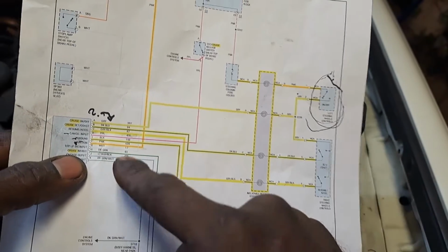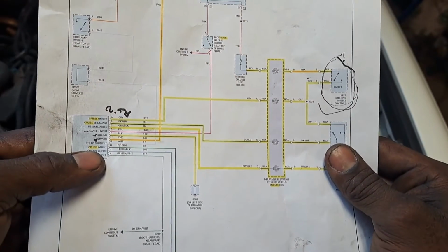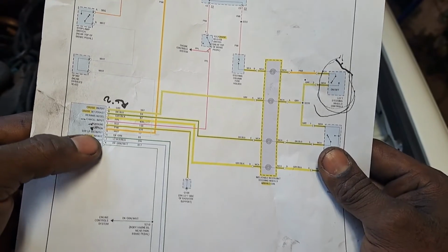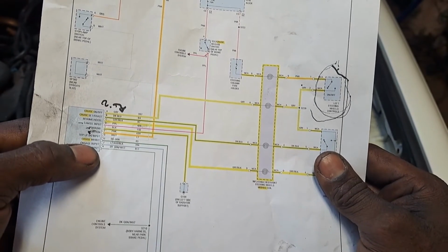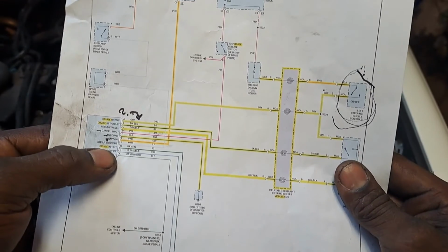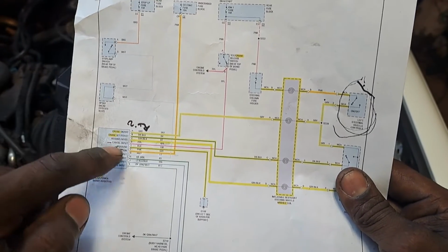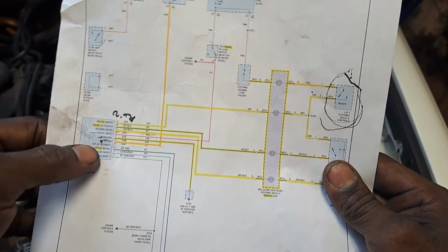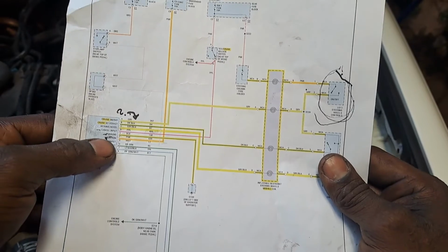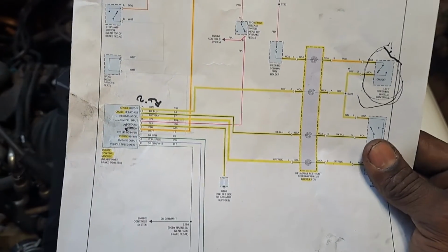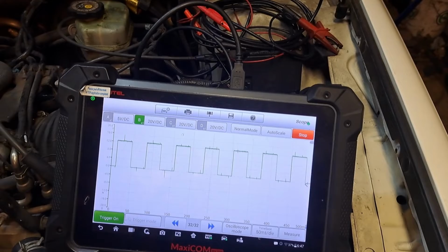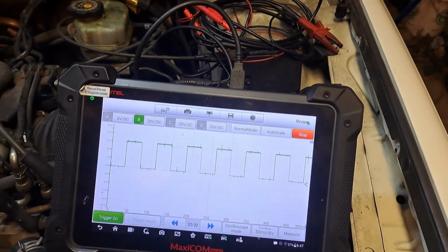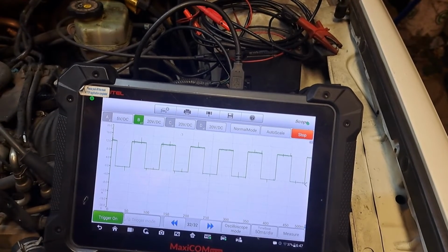After I reach a certain speed, it should actually engage the cruise control with the inhibitor. As for the engagement output, I think this is just going to be sent out when the unit does some type of work. That's what I think. And all the brake switches and everything else are working. We have all the necessary components for a working module, and it's not working. So there's obviously some type of communication going on inside of there that's creating issues.